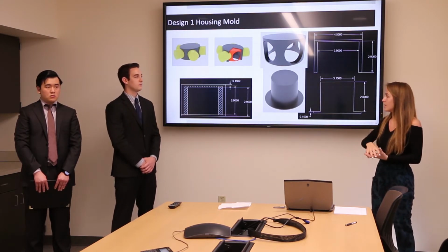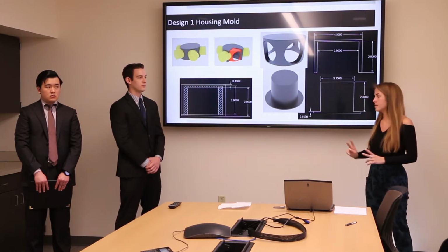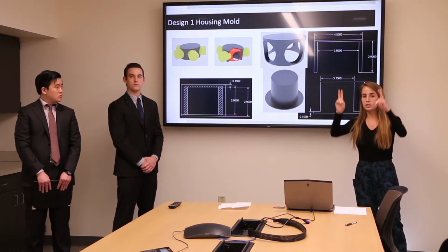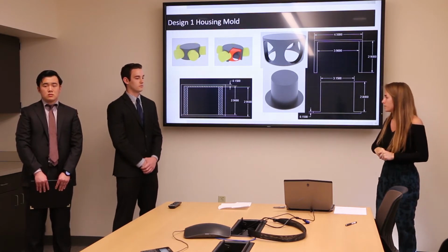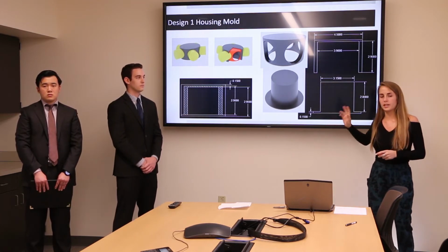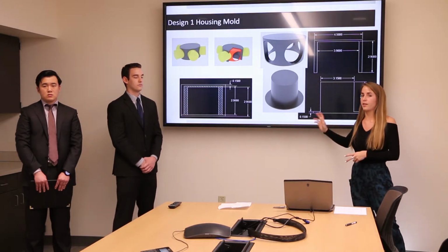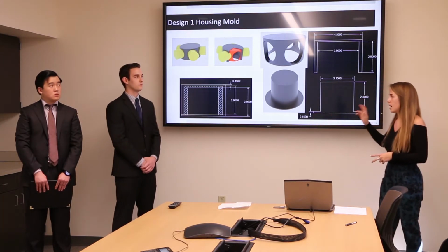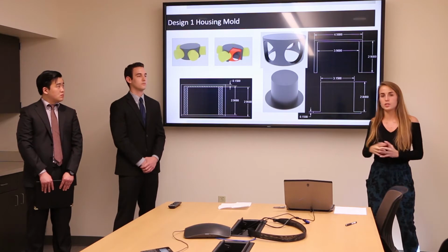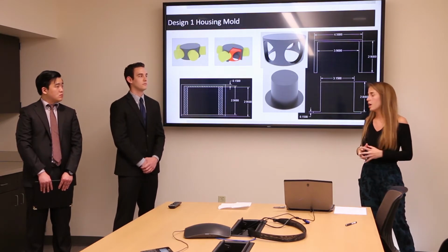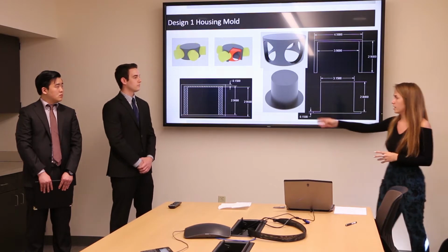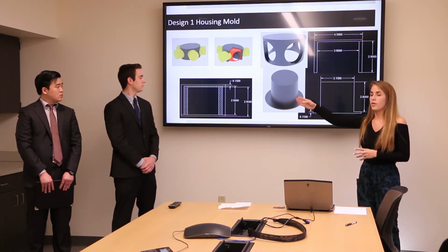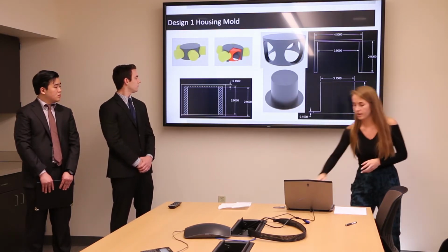And then the mold comes up, and then ejector pins on the bottom push the plastic out from the side B mold. So because of the scope of the project, the ejector pins and the cam pins and the runner are not modeled in these diagrams, but it was just assumed that that would be an effective way of molding. So as you can see, these are the dimensions, and the slash is where the plastic would fill in.